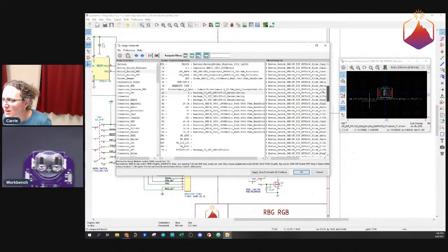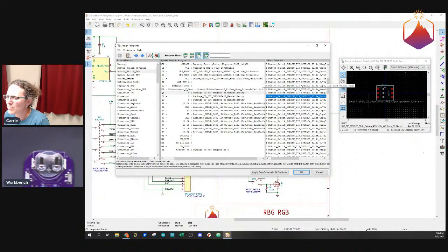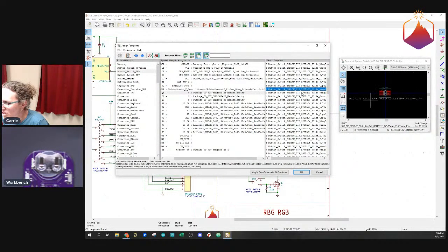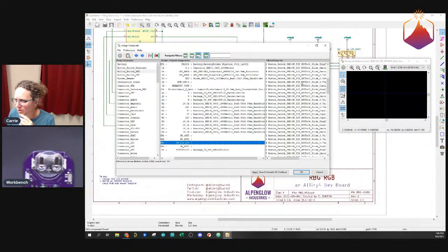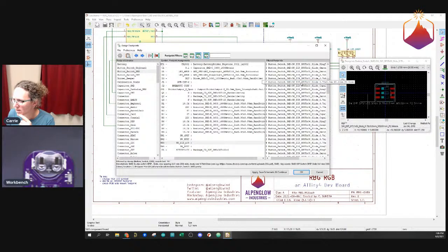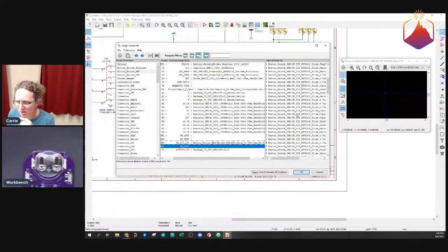All right, so we got dip, slide switch. Yep, that's kind of the style that we want. I haven't actually chosen a component here yet. This seems to be the biggest one, 2.54 millimeters. So it has a tenth inch pitch, which I think is what we want. So we will go over to our dip switch and assign it to our little pattern here. Excellent.